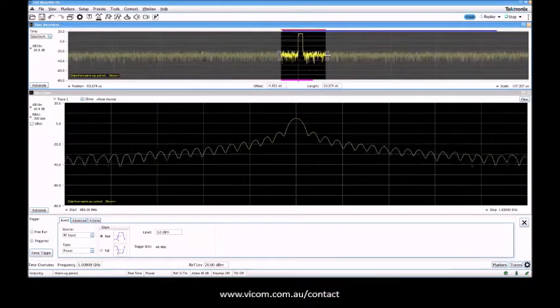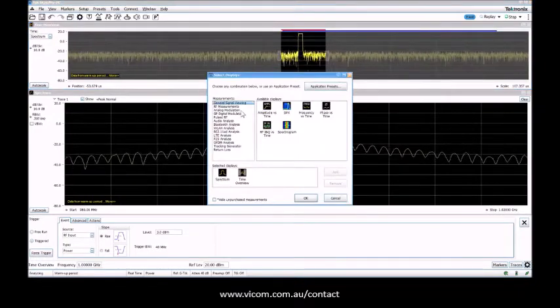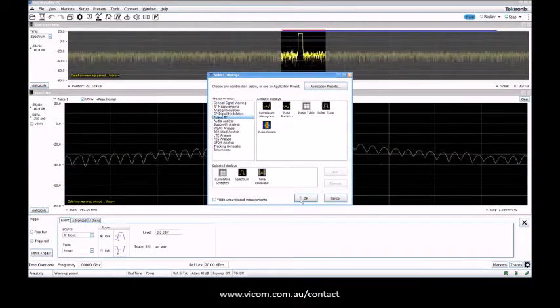Okay, so there are two ways of measuring power. There are actually more ways, but this is a radar-like signal, and there are two ways to do that: from a statistical point of view or a pulse-to-pulse point of view. I will show you how you set up the statistical view first. You go to select displays, you go into what we call the pulsed RF, and we go to cumulative statistics, and just press this one.